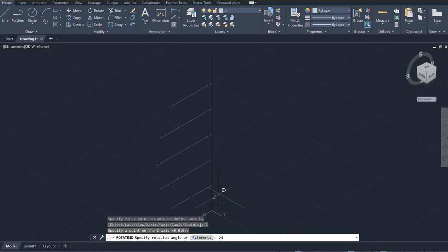Okay, first of all, total rotation has to be 120 degrees. Why? Because we're going to have 3 turbine blades around the 360 angle. When you divide 360 degrees by 3, you get 120. 120 degrees can be obtained in 5 steps, at the increments of 24 degrees.